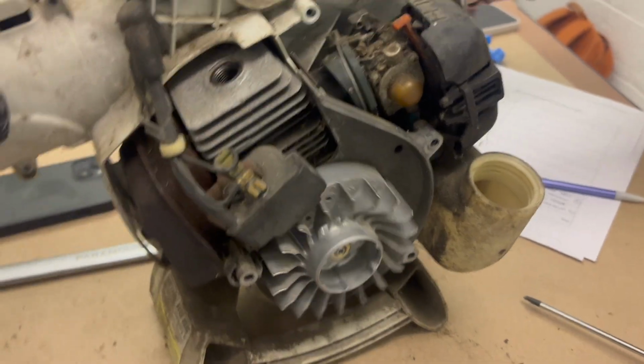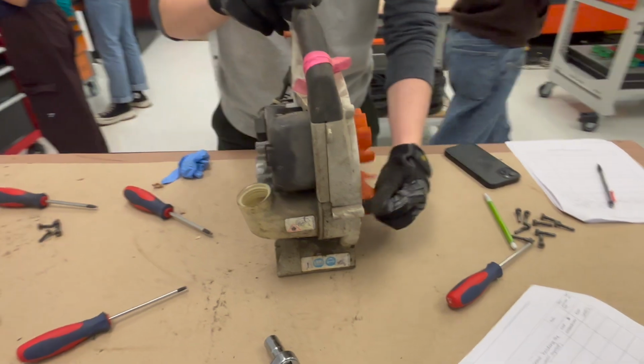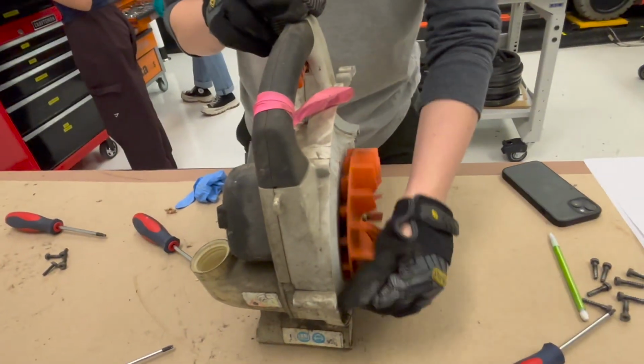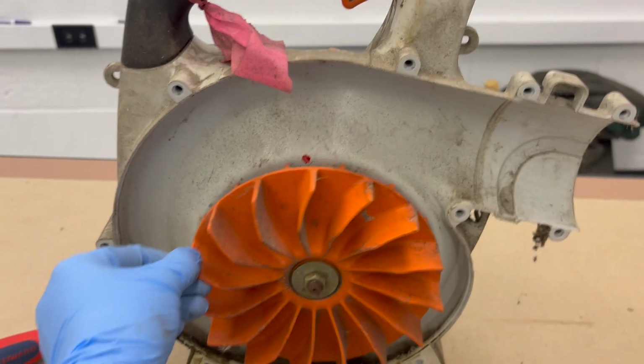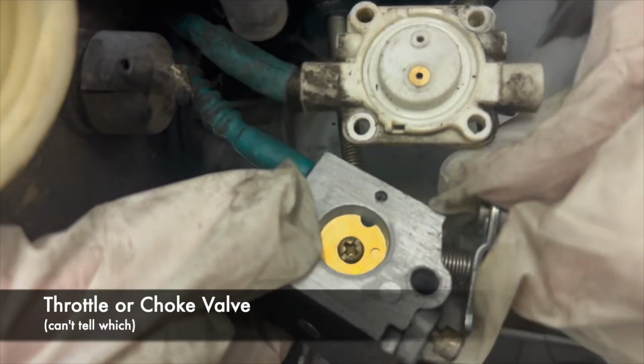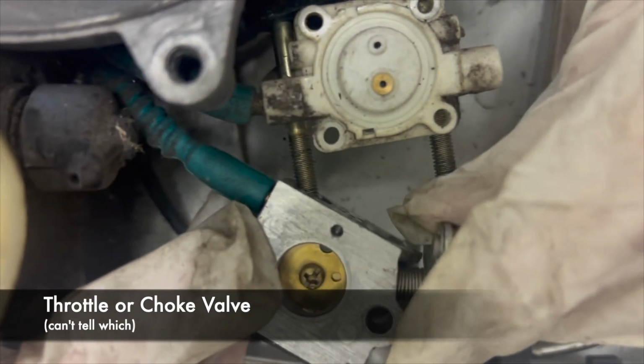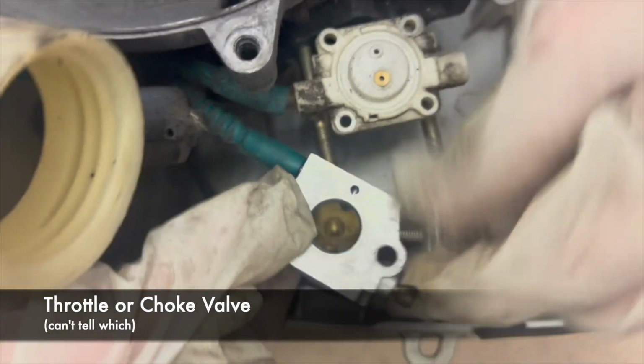There are 2 impellers in this leaf blower, the orange one we examined earlier and the gray flywheel with an opposite blade orientation. The 2 are connected by an axle. The flywheel's main purpose is to cool the engine by pulling in ambient air and circulating it around the hot components. On the rear side of the leaf blower, we see the carburetor, which controls the proportions of fuel and air that enter the engine independent of the output being produced by these moving parts.